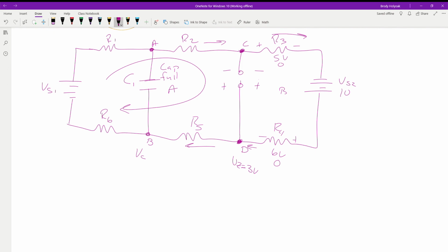I know I didn't specifically go into the very nitty-gritty, but the idea is your capacitor is going to fully charge, and then it's going to be an open. Your diode, you have to remove and basically Thevenize the voltage at that point. Not the resistance, just the voltage. Find out what bias your diode is. If it's a Zener diode, you want it to operate in reverse bias. If it's in reverse bias, how far is it? With a Zener, is it going to take it all? Is there going to be any leftovers? Things like that. And once you get those, then that voltage you'll see split across the rest of the circuit.